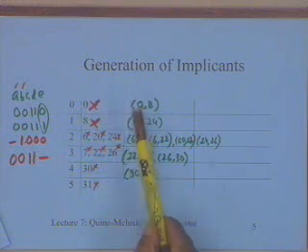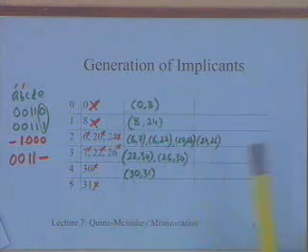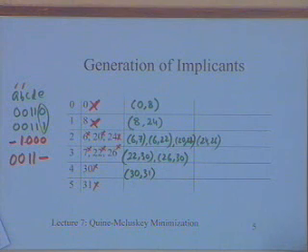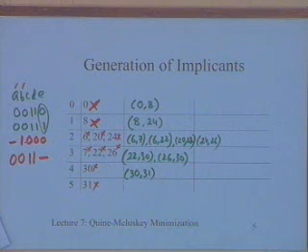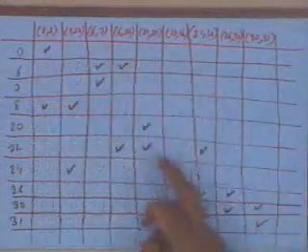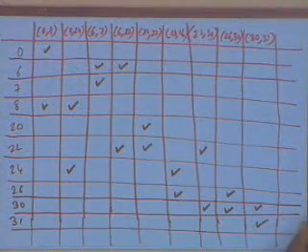So a subset of prime implicants is sufficient for me to ensure that the function that is generated is minimal. A non-prime implicant will never contribute to a minimal function, in the sense that minimality is defined as reducing the number of literals. So my objective is only to choose from a set of prime implicants.